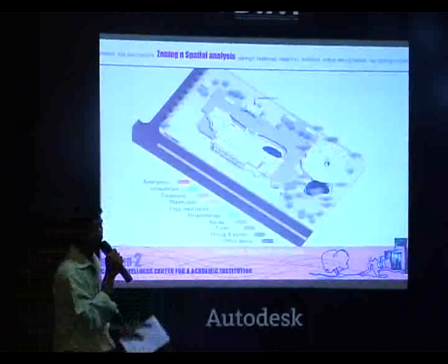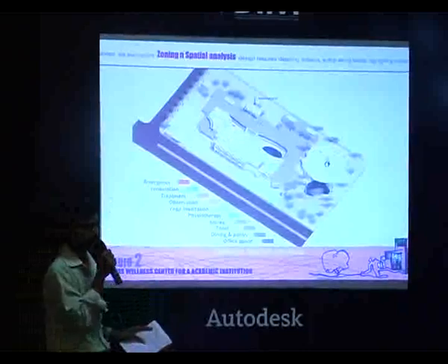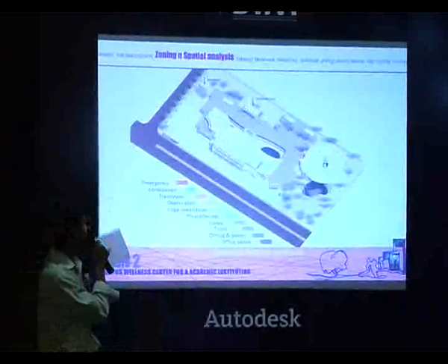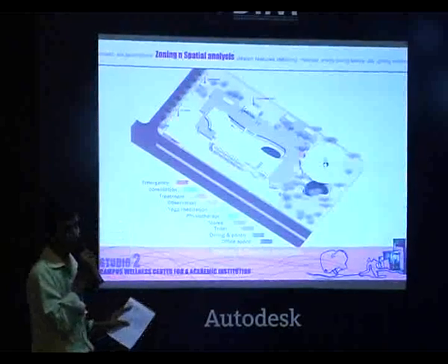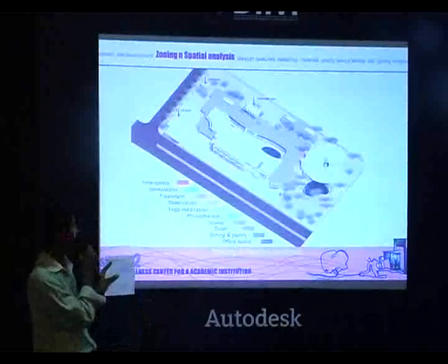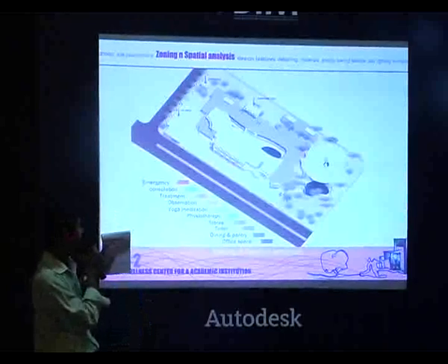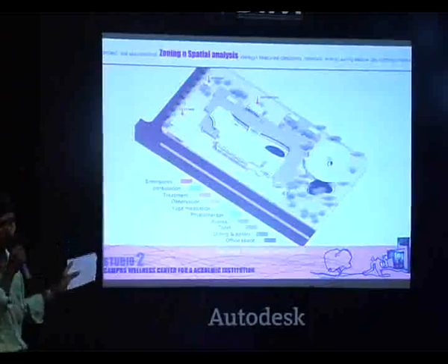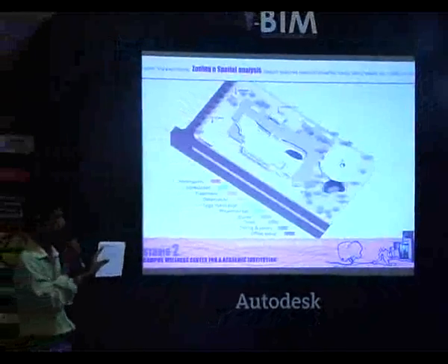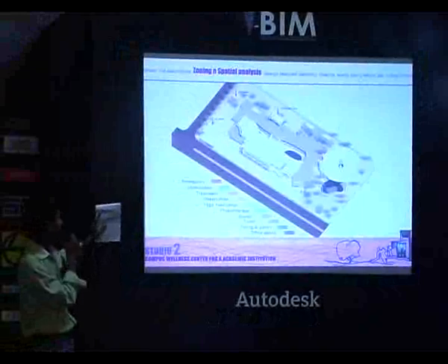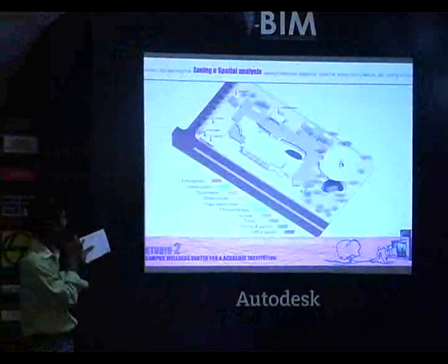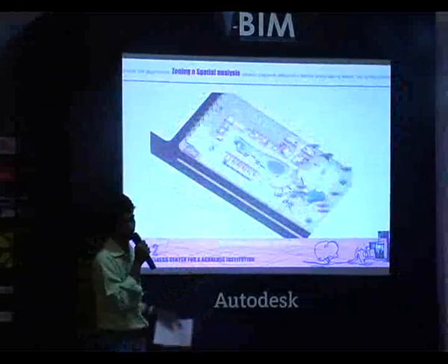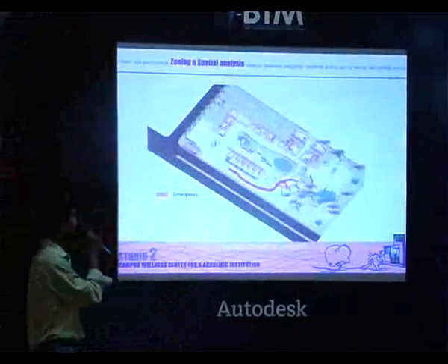Next, we have overhead tanks kept at G+2 level to save energy, so that the water can flow by gravity. And we have the generator kept at the far southeast part of the site, so that the heat generated by the generator can be easily expelled on the eastern side, because there is not much ambient heat available. We have the car park at the entrance of the site, and the driver and security room. We have the ambulance park at the entrance of the site for easy accessibility. Now we have circulation spaces.